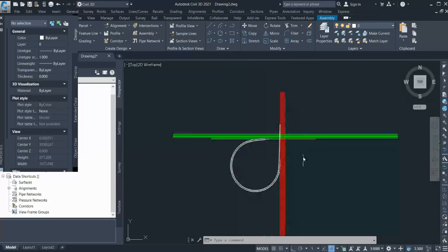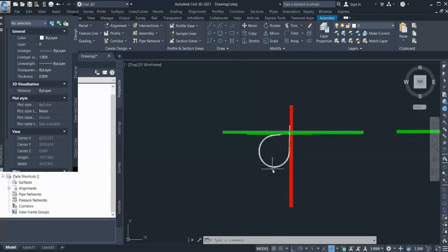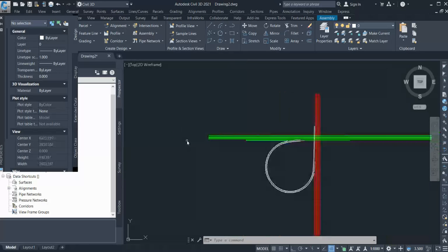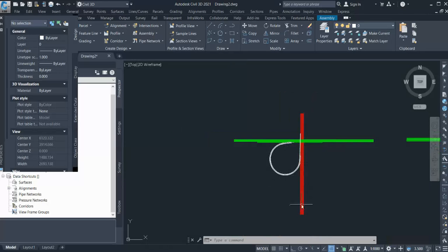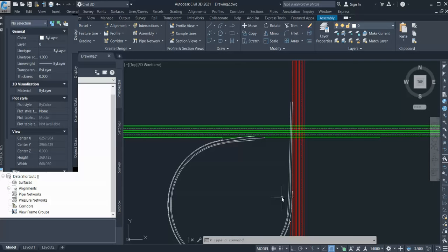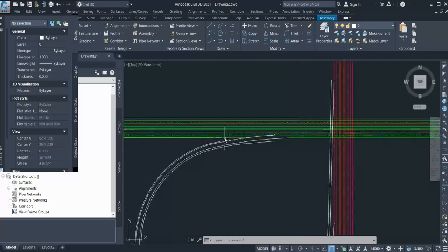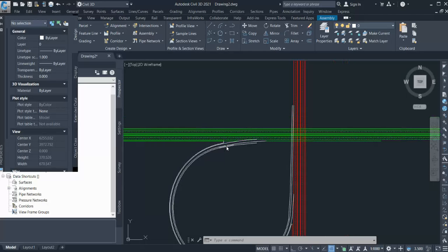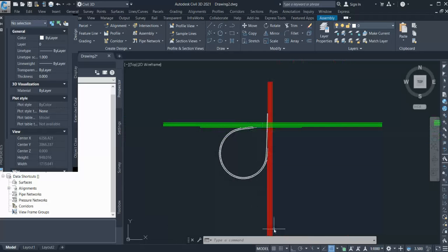Now another thing is to design the loop. Now you have to design some slip lane also. If you have a slip lane, you again have to go with the same diverging and merging value. Everything will be the same. Your nose angle, your nose area, and everything will be the same arrangement. So you need to start somewhere from here.